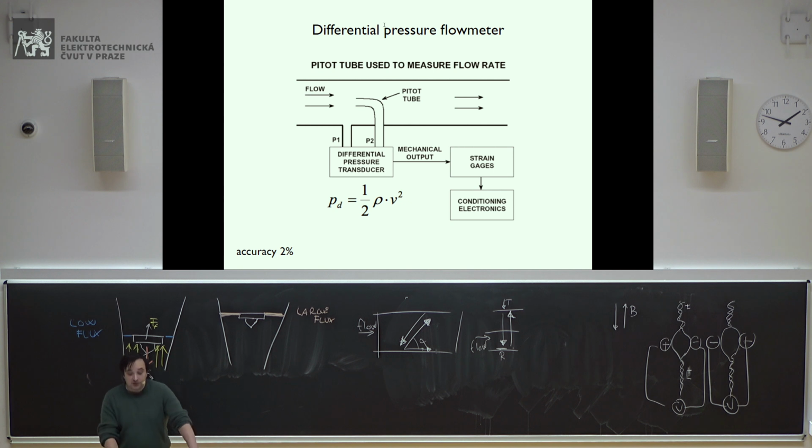Other flow meters. There are pitot tubes. How do they work? Let's assume that you have a tube here in the center of this pipe, which collects the pressure given by the flow at the center. We measure the difference between this dynamic pressure, the pressure given by the flow which moves inside the pipe, and the static pressure, the pressure that you have also if you don't have any stream. If you take the pipes of your flat, there is some water going around, you have some bar of pressure inside the pipes, fine. And you have that pressure even if you don't have any flow, so you cannot use that pressure as a measurement of flow, because it's a static pressure. It's a pressure that you have anyhow, even without flow.